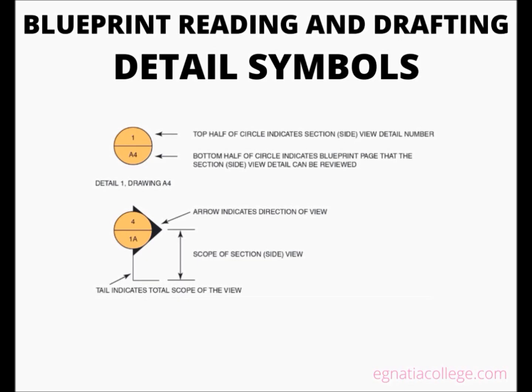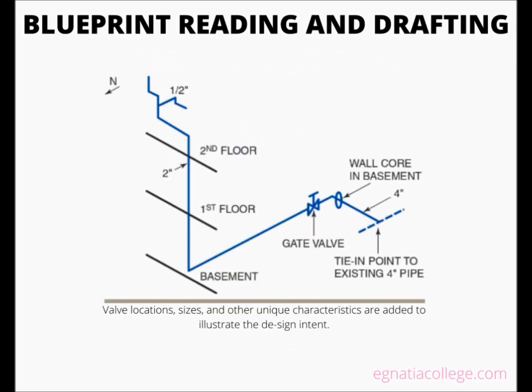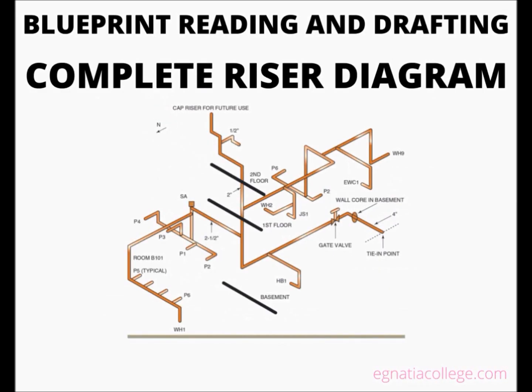Riser diagram. A riser diagram is continued from a simple isometric sketch to a piping system rising through several floors. Valve locations, sizes, and other unique characteristics are added to illustrate the design intent. A complete riser diagram should include all abbreviations, sizes, and possibly an abbreviation legend.